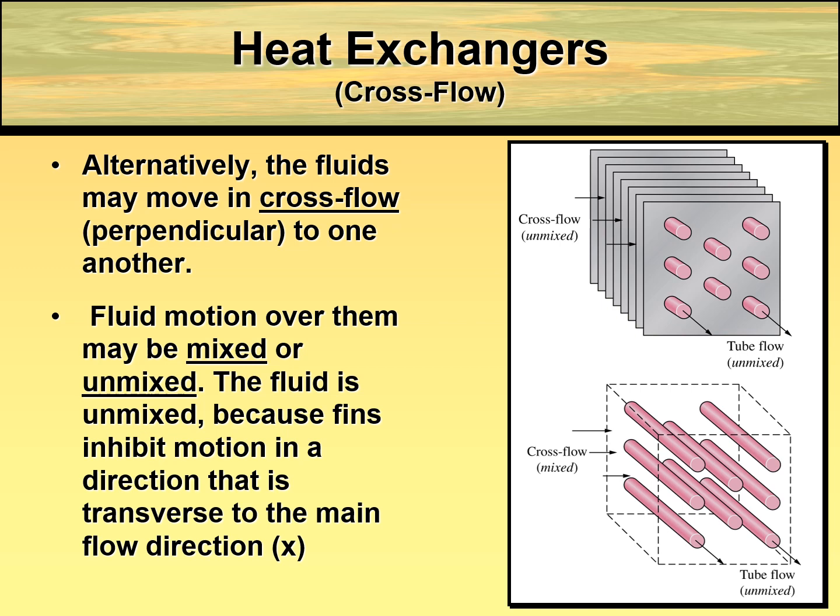And another flow arrangement is called cross flow, where there are two types of cross flow: cross flow mixed and cross flow unmixed. So this is cross flow unmixed, and this is cross flow mixed. For the cross flow unmixed, the flow is separated, which is the flow coming across the tube. They are going to be separated or guided by the fin.